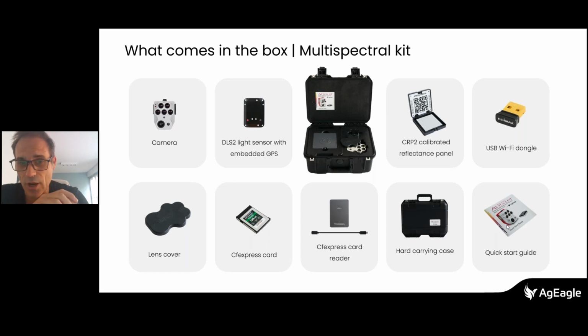The Skyport option also gives you the integration, so you can work with the DJI Flight app and have access directly to the camera, and you can see each time the camera takes a picture. Wingtra provides its own mount, so if you want the mount for the Red Edge P from Wingtra, you need to buy it from them. But you can swap the camera, put on the Skyport, and put it on a Matrice 300. There is absolutely nothing that will not allow you to do that.